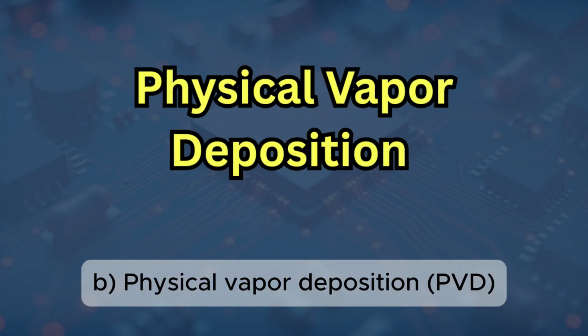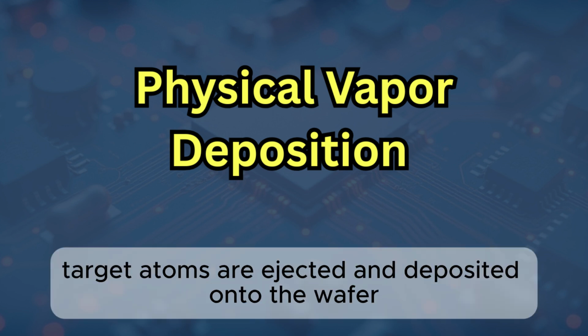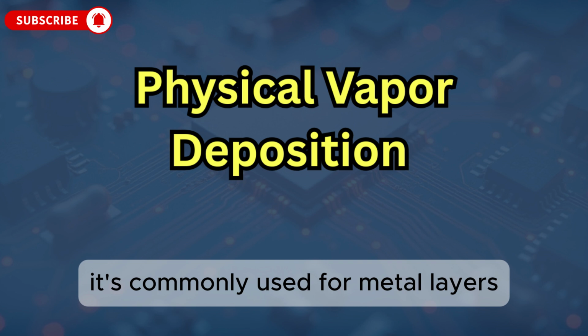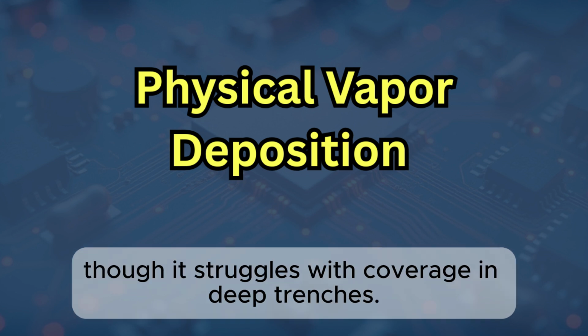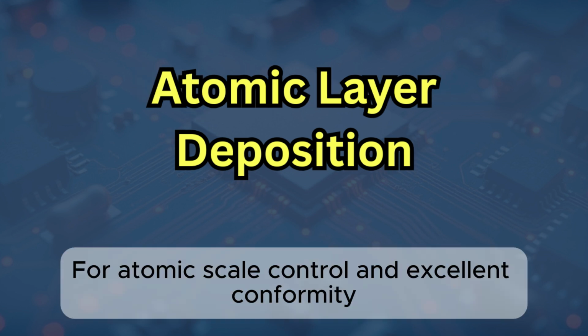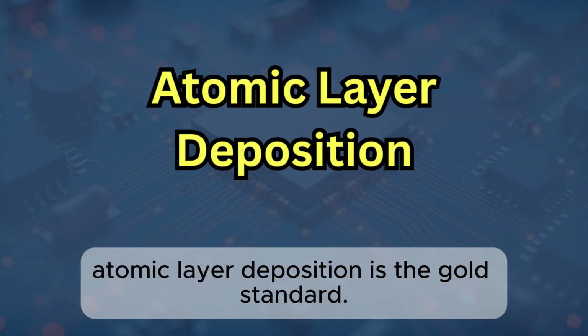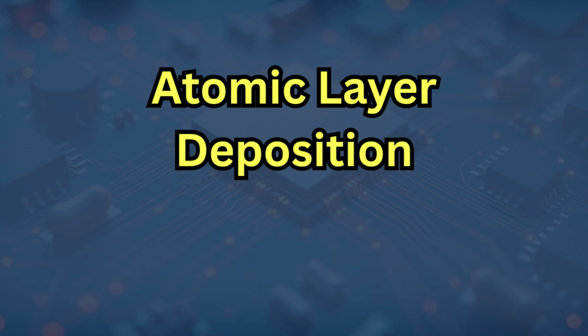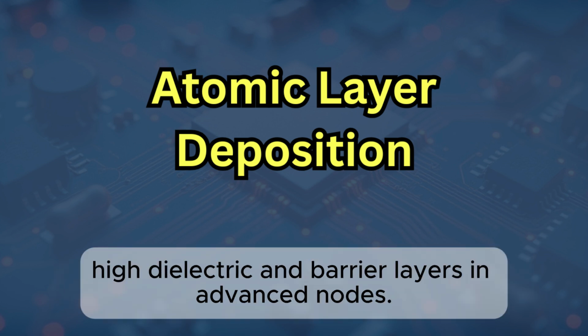B. Physical vapor deposition. In physical vapor deposition, such as sputtering, target atoms are ejected and deposited onto the wafer. It's commonly used for metal layers like aluminum or titanium nitride, though it struggles with coverage in deep trenches. C. Atomic layer deposition. For atomic scale control and excellent conformity in extreme aspect ratios, atomic layer deposition is the gold standard. It relies on self-limiting surface reactions, perfect for ultra-thin high-k dielectrics and barrier layers in advanced nodes.